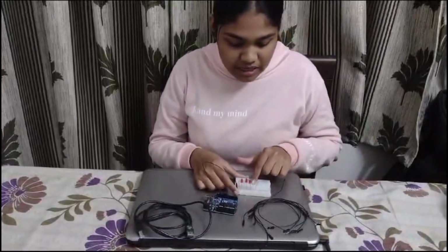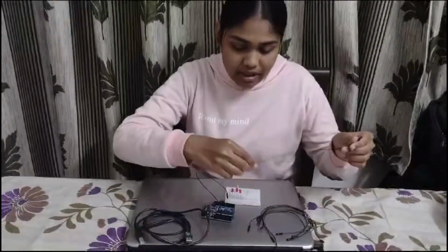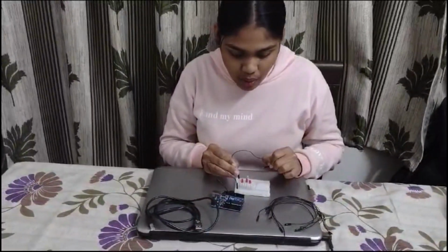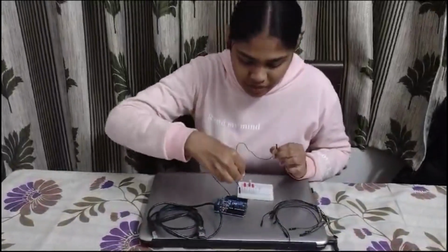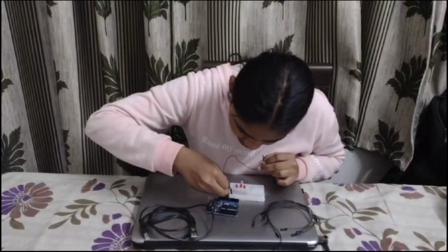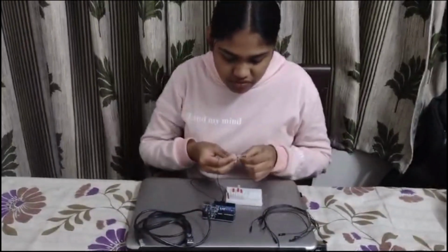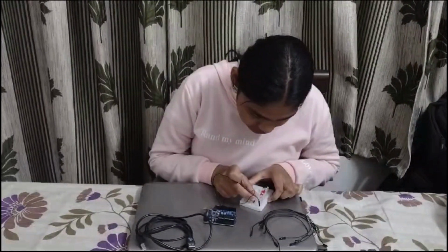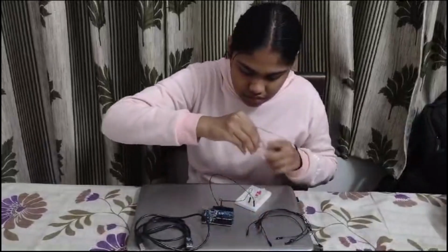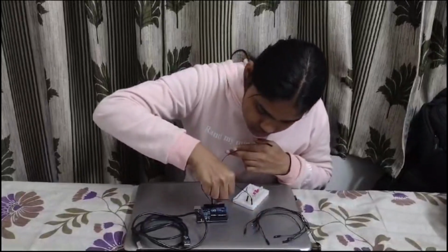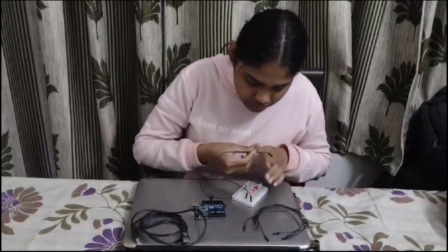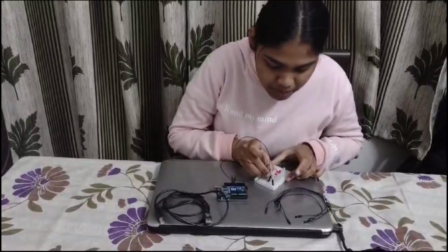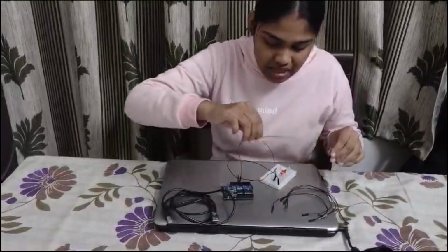After the LED pins are done, now we have to connect the jumper cables. For the LEDs you can select any digital pin. I am selecting 10 for it, and I am keeping consecutive numbers for the rest. The digital pin should be in the same row the LED pin is in. Make sure that the LED pin row, the digital pin row and the cable's row is the same.